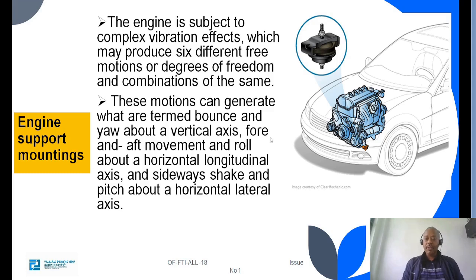Engine support mounting. The engine is subject to complex vibration effects, which may produce six different free motions or degrees of freedom and combinations of the same. This motion can generate what are termed bounce and yaw about a vertical axis, fore and aft movement and roll about a horizontal longitudinal axis, and sideways shake and pitch about a horizontal lateral axis.